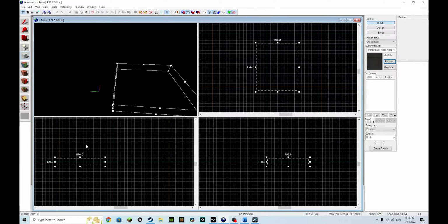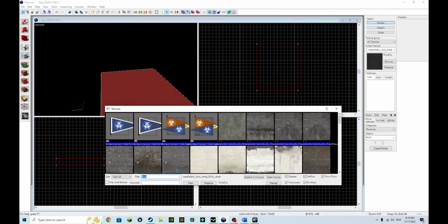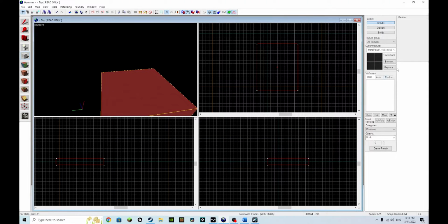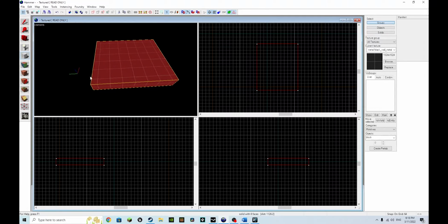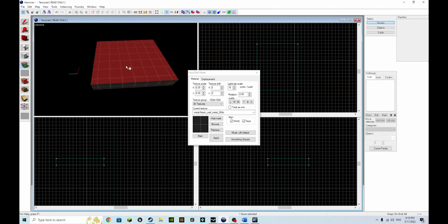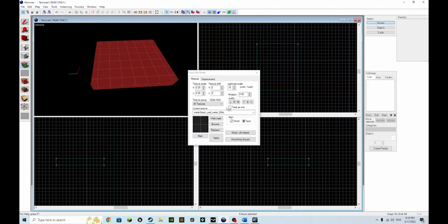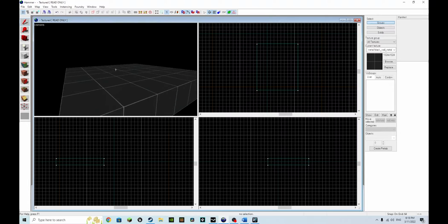And also then you can select a wall texture on the side here, like this texture, and select this to apply it. And our texture is not equal, so I'm going to use the face edit tool to hopefully select every face, and then hit LT, hit apply. You don't really need to hit apply, but I do it anyway. And now our textures are perfectly aligned.